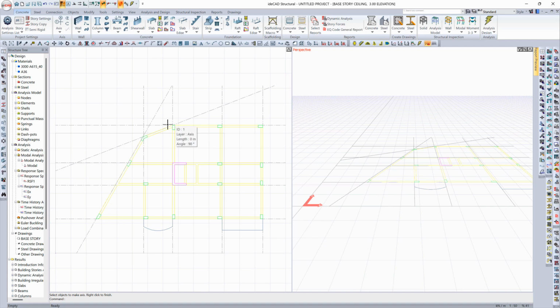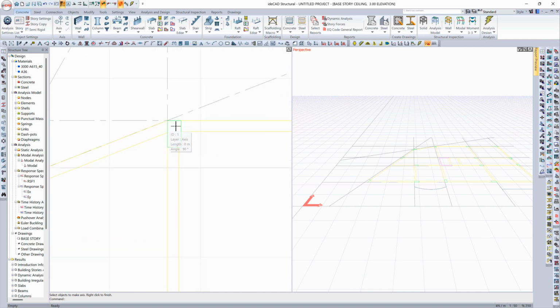Once the drawing is imported, if you know the size of an existing column, you can measure it to check that the import scale is correct and that there is no mistake. To do this, I click the distance icon on the toolbar.